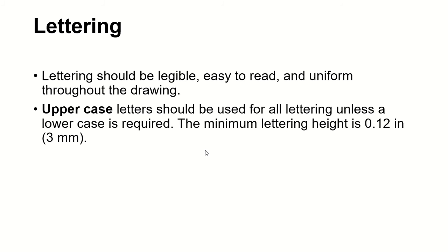Uppercase letters, you're going to use them for lettering. Lowercase letters, you're going to use them when required. Minimum lettering height is 0.12 inches, about 3 millimeters. Lettering height means the height of your letter, so you're going to keep it at 0.12 minimum.